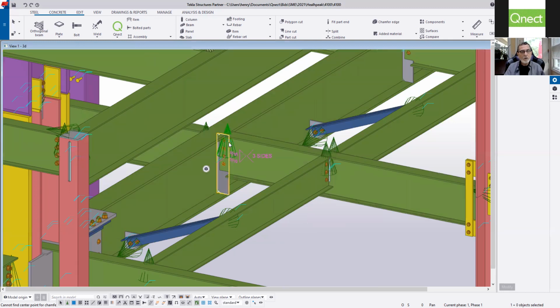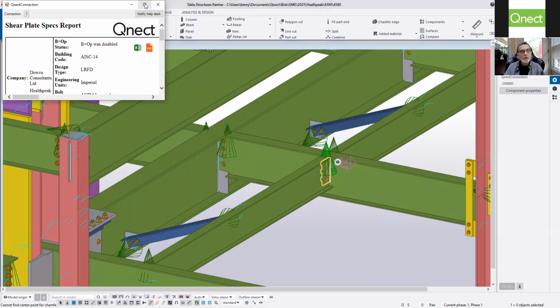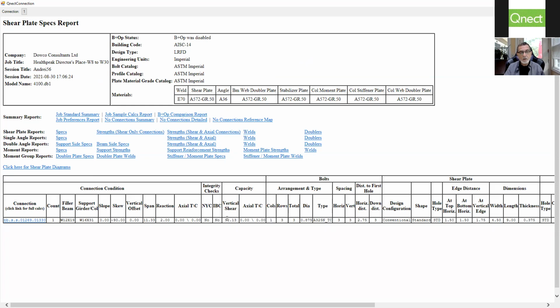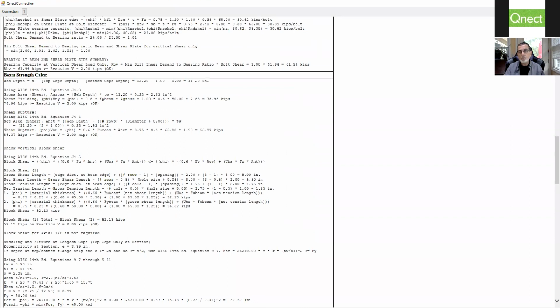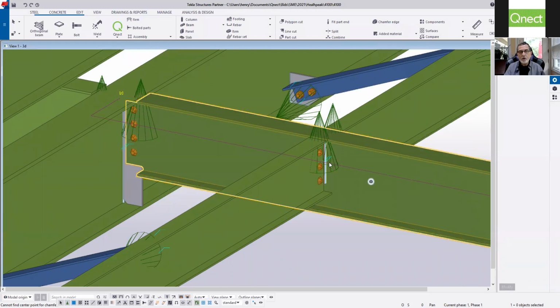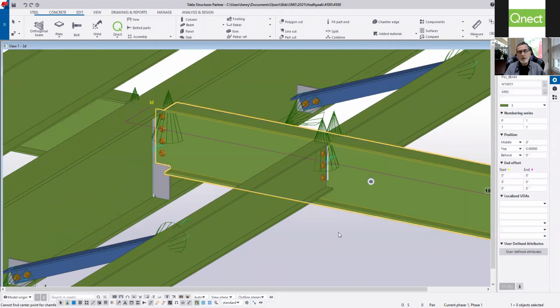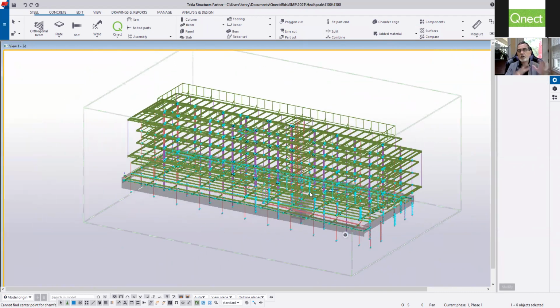If you click on the cone, that one's a macro, you'll get the engineering information, the capacity, and all of the limit state engineering output, which, by the way, is accumulated as a package for the PE stamping. The connection has all the welds, the cuts, the copes, so it's a complete section. It's ready for translation into an EPM file structure that would go right to PowerFab, where the unit cost would be applied and then entered through the system.